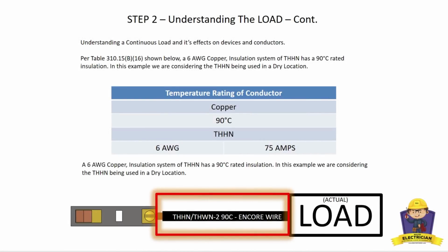All right, so what we did here is we simply pulled out the more relevant terms. We're using a 6-gauge insulation, THHN, 90 degrees C rated, because that's what THHN is. HH is 90 degree. 1 H would be 75. No H's would be 60. All right, so 6-gauge copper. We're dealing in copper. Under the 90 degree column is good for 75 amperes.